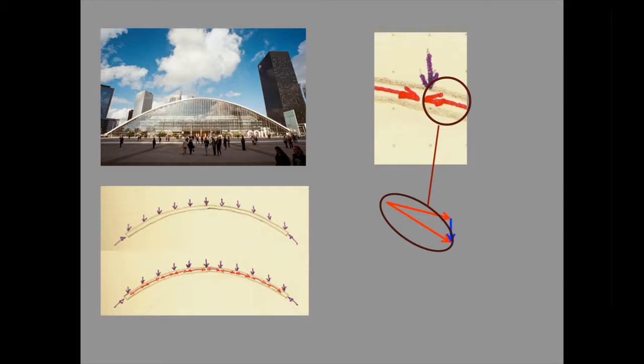Note that the second red arrow, representing the force going into the part of the shell to the right, is longer than the first, indicating that the internal force in the shell increases downwards towards the foundation, as one would expect. Note also that the direction of the second arrow is changed downwards, and this is a very important point because it means that if the axial internal force only condition is to be maintained, the direction of the shell must change by exactly the same amount. This little interaction of internal force and load is of course occurring all the way down the shell.